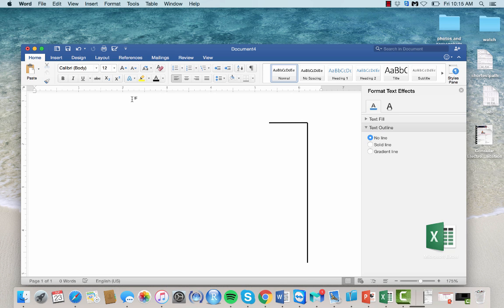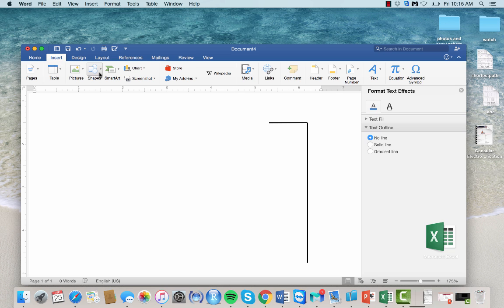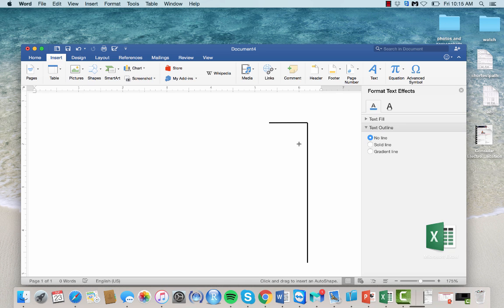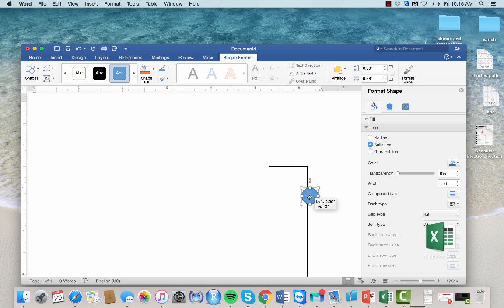And since it's an operation chart, we're going to be putting circles and squares on it. Circles will mean operation and squares will mean inspection, not inception. Okay, so let's start with our first operation. I'm going to be drawing a circle here, and you see the central line here. I'm going to be aligning that line with this vertical line that I drew.